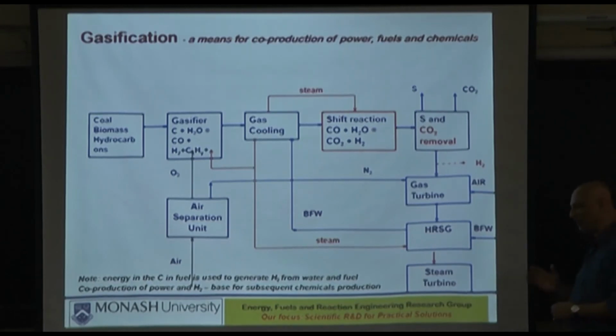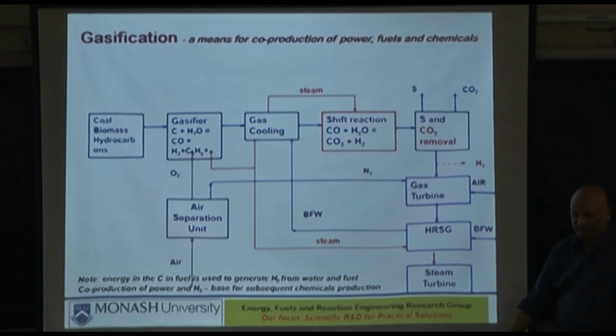You need to run it at a temperature so that all the carbons are converted somehow, and hopefully converted mostly to CO and less to CO2, just enough to supply the heat, right. So, there is the balance. So, this all can easily come from simple thermodynamic calculations.